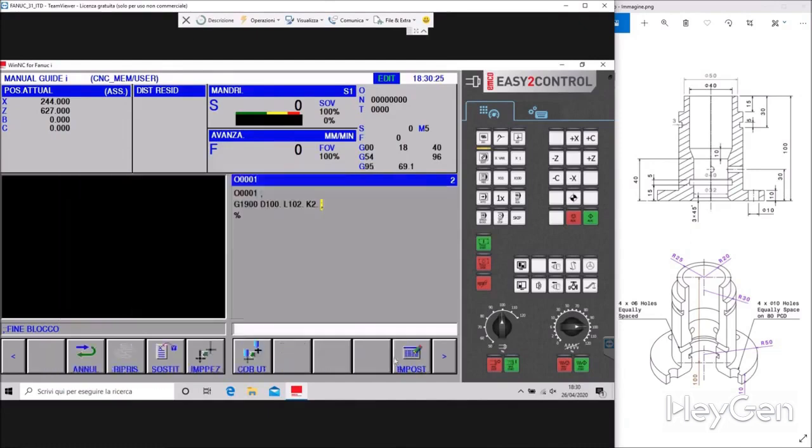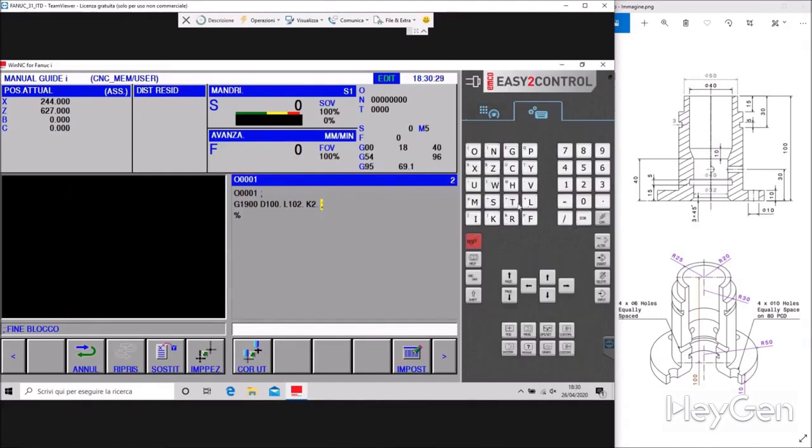So let's close the tool correctors page and go to insert our corrector. T11, 11, and insert. Rather, we work with soft keys, excuse me. We delete this T11 working with soft keys. Here too, we have this, which is the turning manual guide page. You see that it is the round piece. Otherwise, there is the milling manual guide page. You see that we have a square icon.